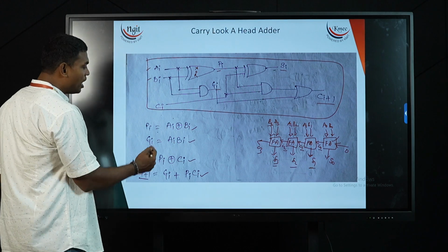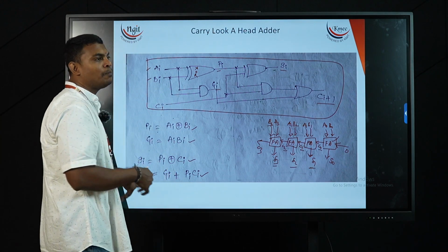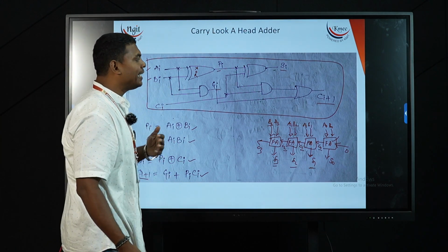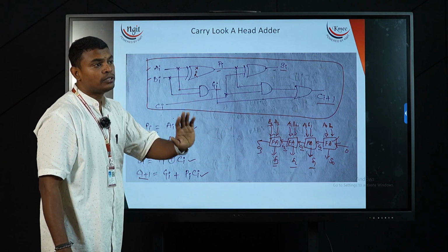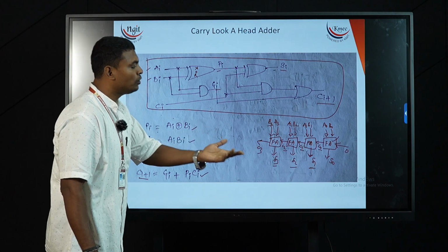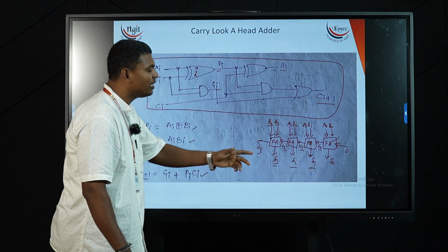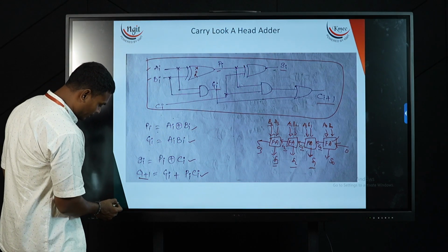Now let us see how these formulas will help me avoid carry generation and propagation delay, and how, without waiting for the carry, I can generate my S1, S2, S3 values. Let us see them.